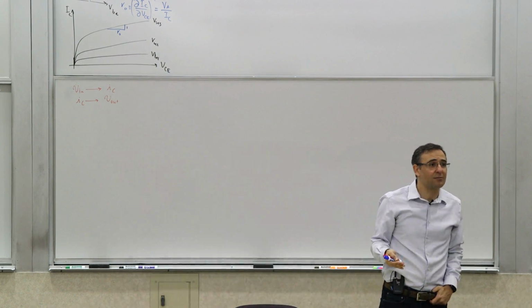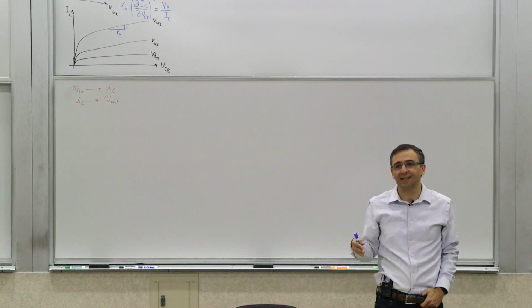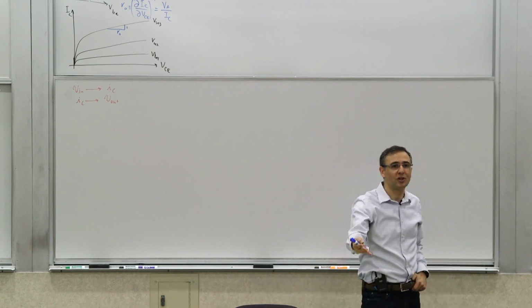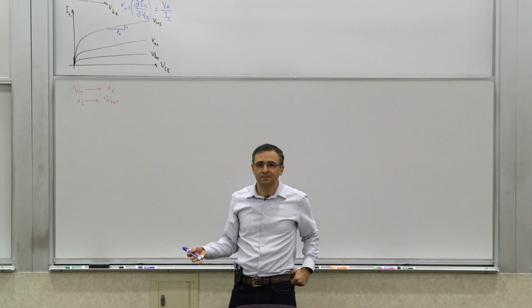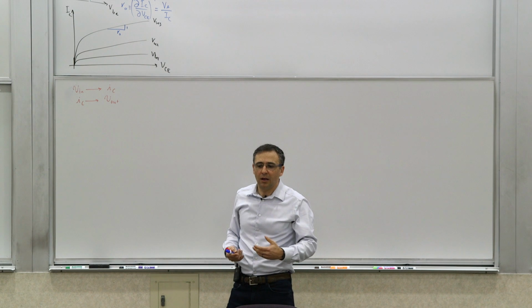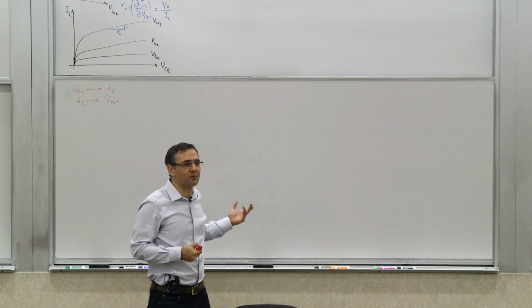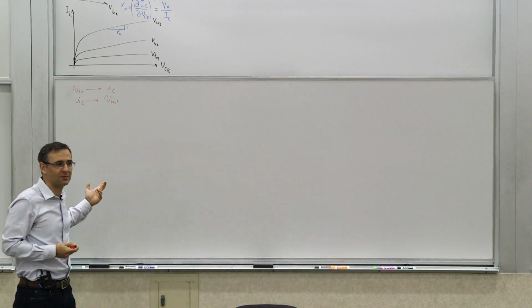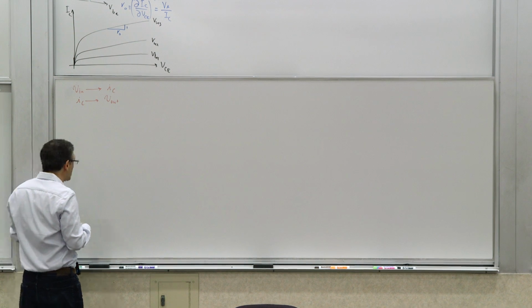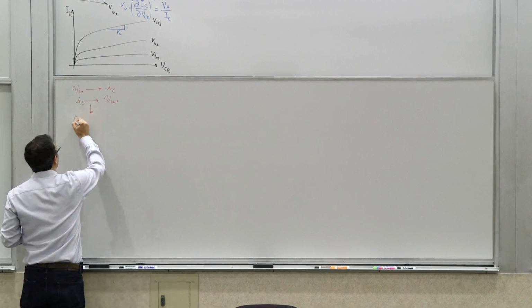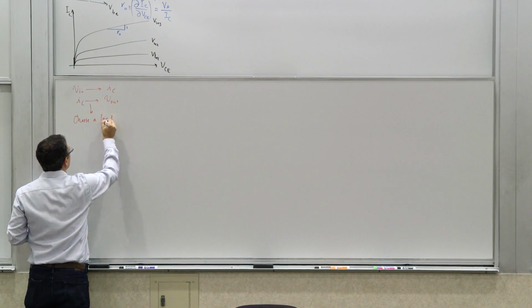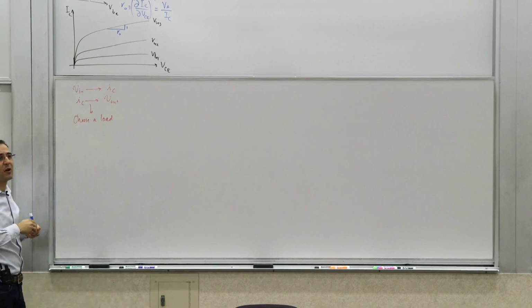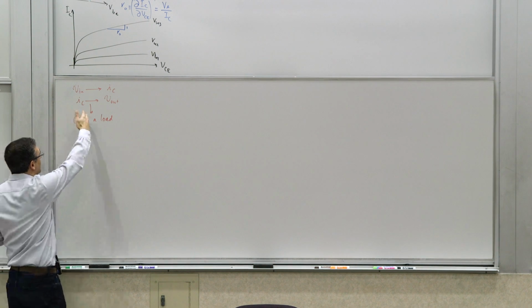Some of them are dictated by the requirement to use the minimum number of passives and maximum number of actives if you're on chip, and things of that sort. So a lot of our discussions would go into this choice of load. But that's where it's coming from. So we have to choose a load, something to convert the current to the voltage.